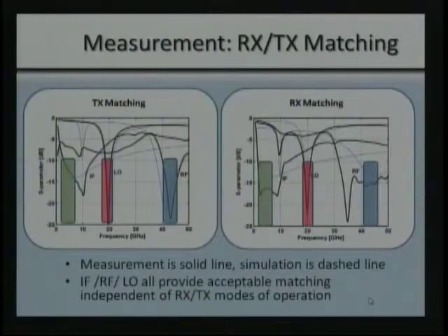To show you that it worked, I'm going to first describe the matching in the 2 modes. So the very important thing that you'd like to see to prove that the PALNA concept works is that under the TX modes and the RX modes, the matching is under 10 dB.